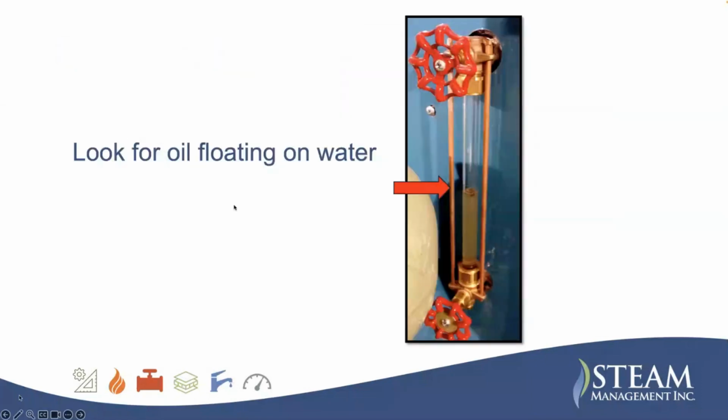And yeah, if you think about the steam leaks, they're all coming through when they first form. They're coming through at choked flow, so it's as high a velocity as could possibly go through there with the pressure, and so they erode the pipe even further. So it quickly makes the situation worse. That's why the safety relief valves leak, like you were saying. They erode the seal there.